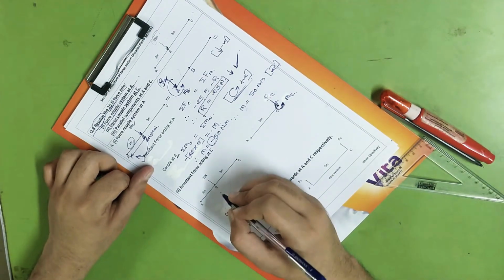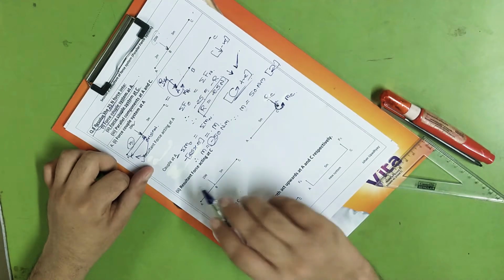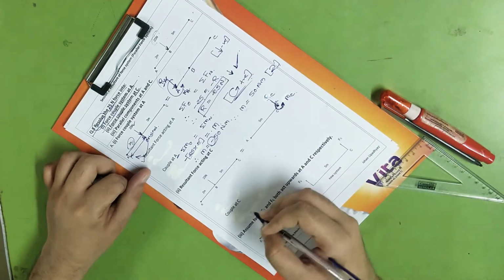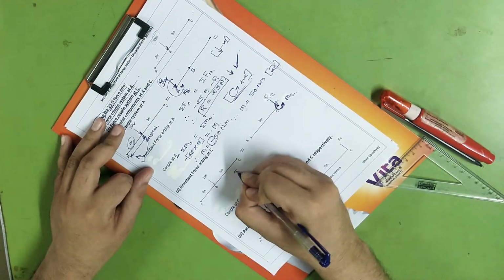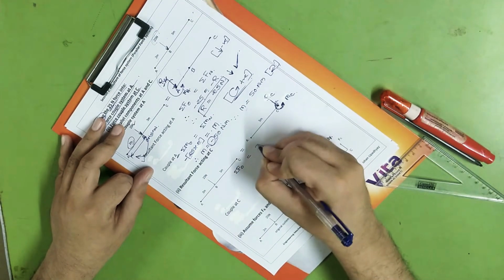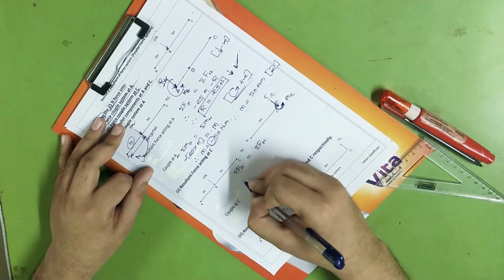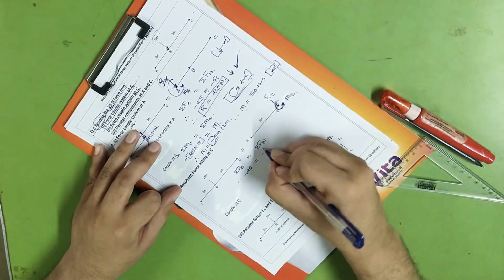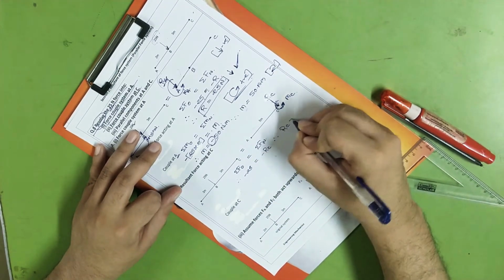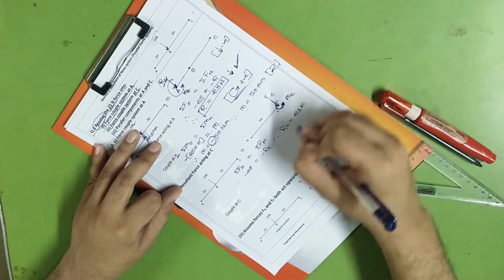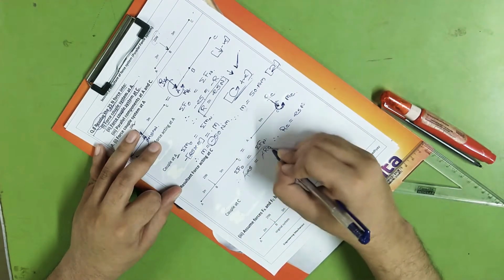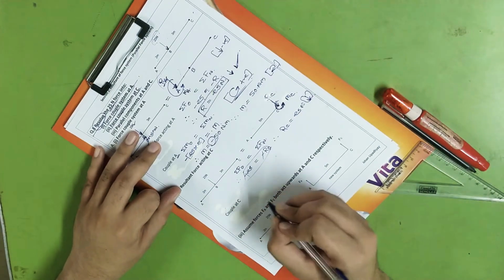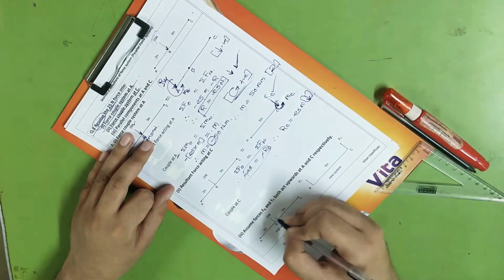Now again we have resolved this 25 Newton into a force and a couple system at C. Then I can say that these two systems are producing the same effect. With this I'll say summation of force of original system is equal to summation of force of new system. That implies that here I'll say minus 25 is equal to minus RC, and therefore RC is equal to 25 Newton. Since the minus gets cancelled out and I'm getting a positive answer, whatever direction I have assumed is correct. So I have calculated the value of RC.